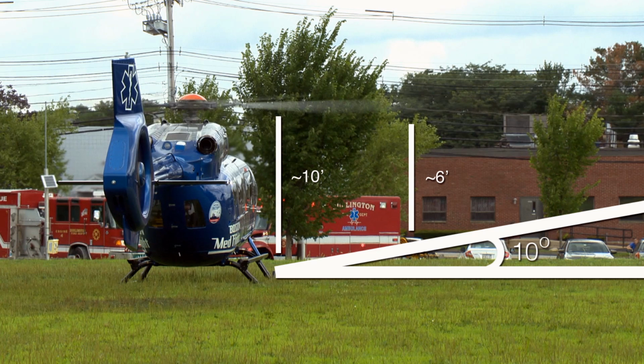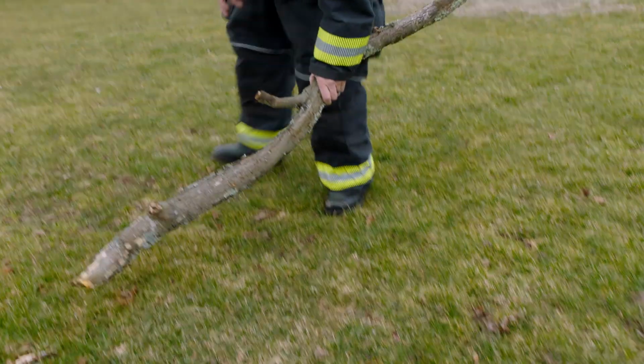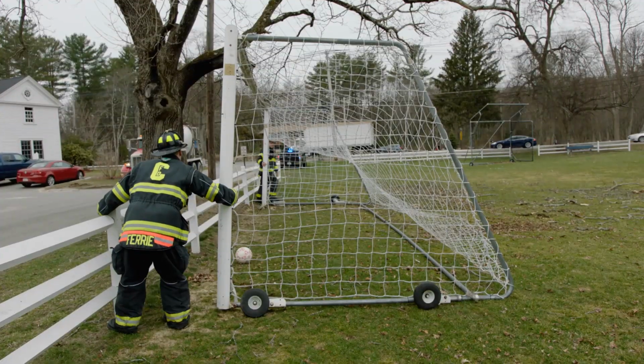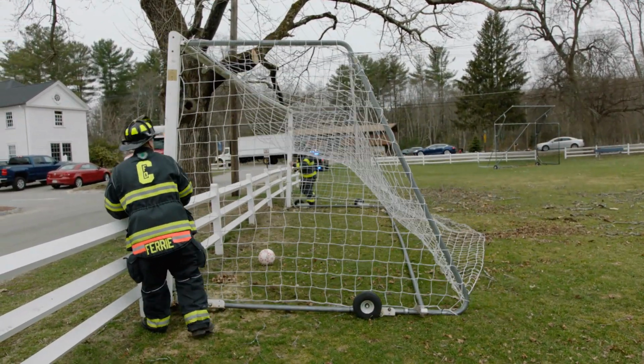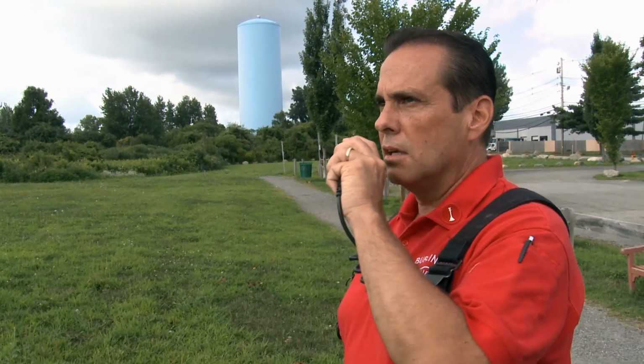Severe slopes reduce the distance between the rotor blades and the ground and can pose a hazard for anyone approaching the aircraft. Personnel should survey the LZ to remove loose debris and make note of obstructions that are in the ground and a water tower to the west and in the immediate area.